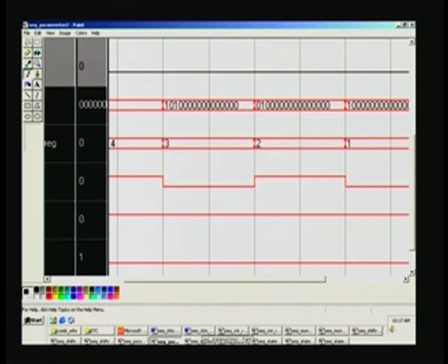This is a general question. You talked about always at positive edge, negative edge. How do you go about doing level triggering? The level is same. I mean, you sense the level, immediately take action. It can be within the sequential circuit or outside it. If it is outside, you can use an assign statement, a mux statement you can have. If a particular level is 1, immediately let the output change using an assign statement.